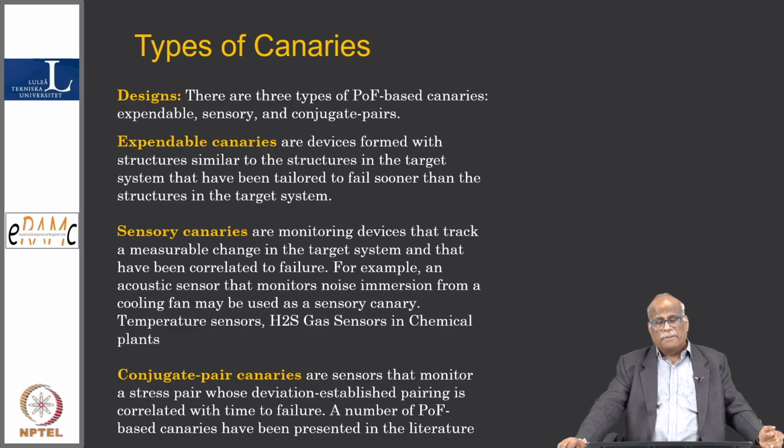For example, let us say there is a pump operating in the field. One sensor is that I put my hand there and feel the temperature. So I get advance information because it has not failed. In fact, it would have continued for a couple of days or months also, but a decision is taken. Similarly, with a bearing, before failure the vibration level goes up and it is reflected in the sensors as noise, and that noise can be sensed.